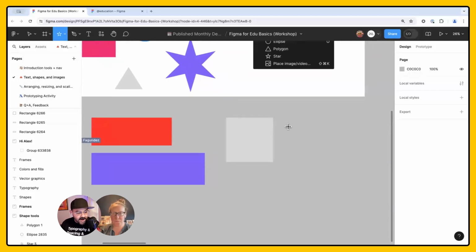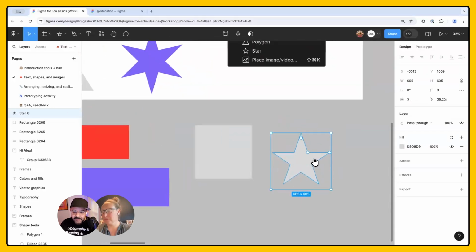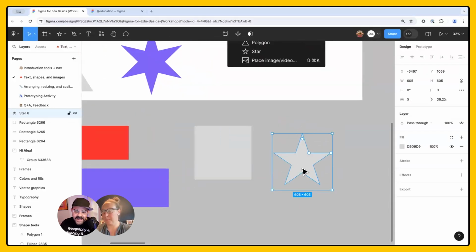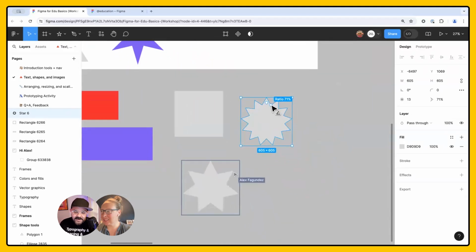When I click on a star, I'm going to click and drag right here. And you see this little triangle that I have here available. These little dots in Figma signify that this object has some secrets. So if I'm making, let's say, a little sign here that I need a star, and I want to make like 99% off or something, I can change the properties of this star. I could change the amount of points, and I can drag it right there.